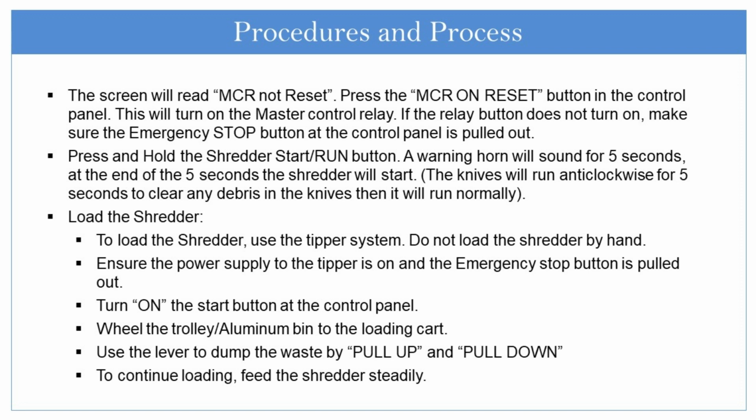To load the shredder, use the tripper system. Do not load the shredder by hand. Always use the tripper system. Ensure the power supply to the tripper is on, and the emergency stop button is pulled out. Turn on the start button on the control panel.